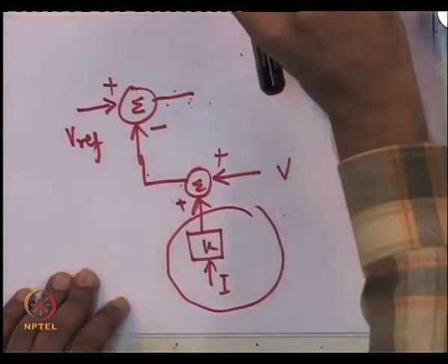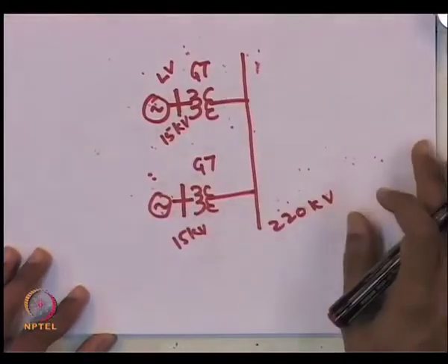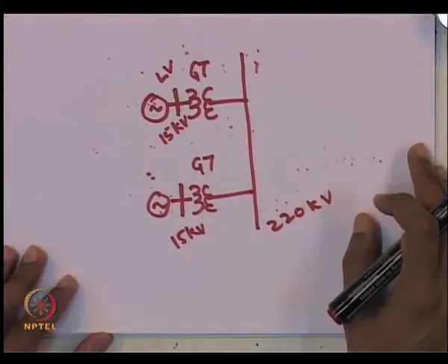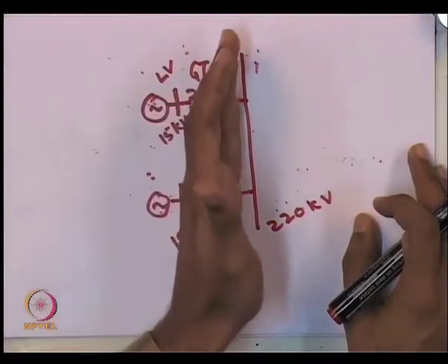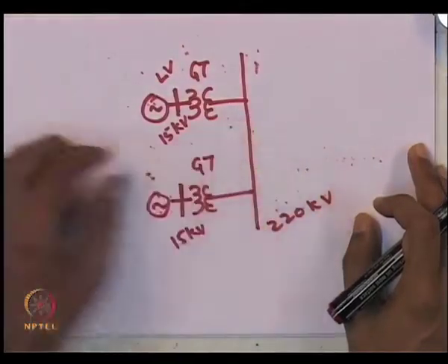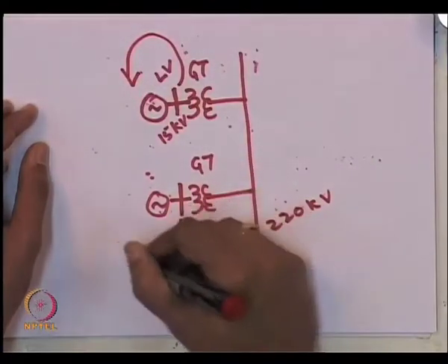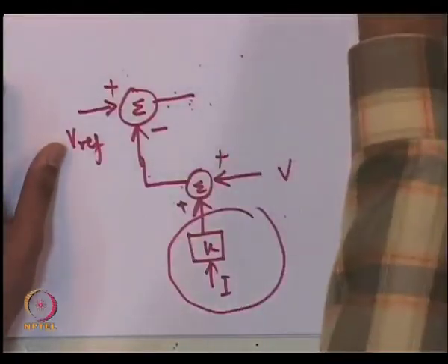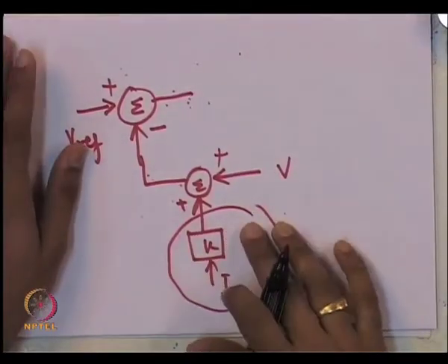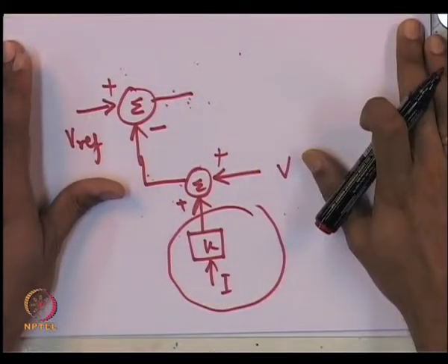It is usually not used in situations where a common objective is not being met by two excitation systems. For example, in this case, when the machines are bused together at the high voltage side and your voltage regulator is trying to maintain these voltages constant, it is not necessary to apply this load compensator, and in such situations it may be absent. So, please chew upon this point.